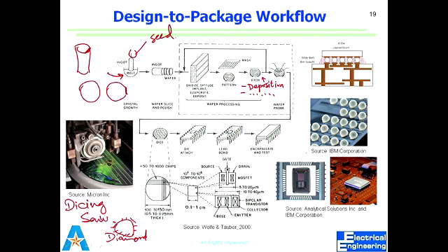We'll see why that is important, but for now just focus on this: we make those wafers, we put them in a furnace, we oxidize them, we may incorporate impurities, of course. A semiconductor has to be doped to become electrically active. And we then use masks to pattern. We may etch, we may deposit, we do the whole process a few times, and then we end up with this wafer which has a distinct number of dies, and then we test the devices on those dies. Right? Makes sense?